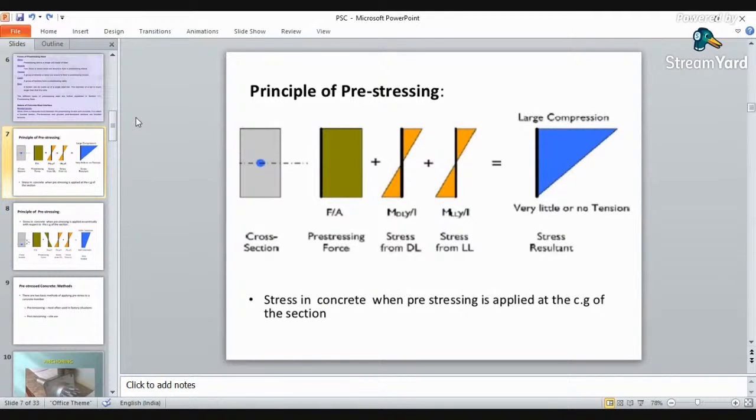Then, how your pre-stressing works. Now there are two more definitions before going into the principle of pre-stressing, on how your concrete and steel interface is there. That is how your concrete and steel are connected, either they are bonded or not. So the nature of interface is classified as bonded tendon and unbonded tendons. Bonded tendons are when there is adequate bond between your pre-stressing tendon and concrete, then it will be termed as a bonded tendon. Pre-tension and grouted post-tension tendons are your bonded tendons. When there is a perfect bond between concrete and steel, then it may be termed as a bonded tendon.